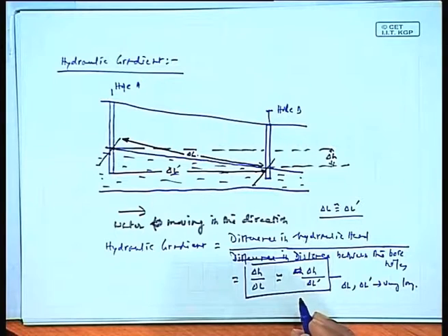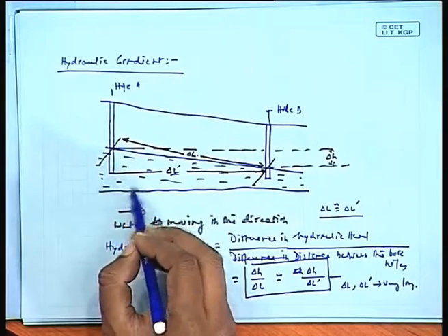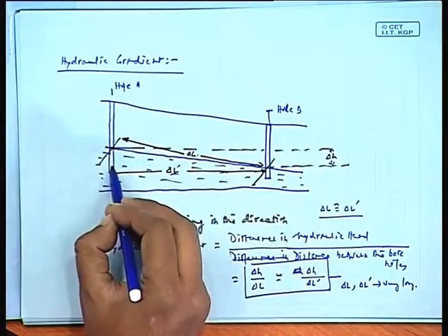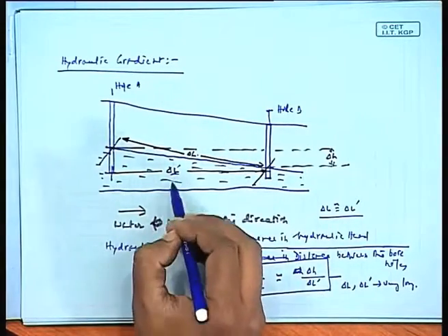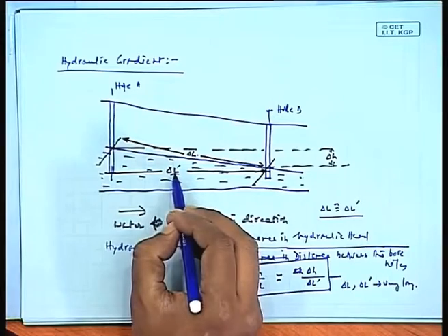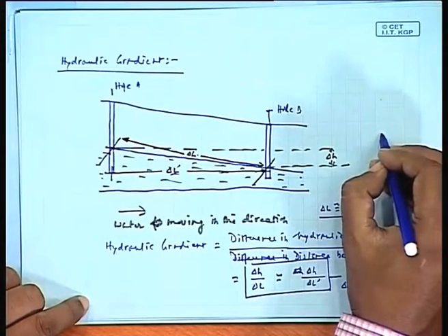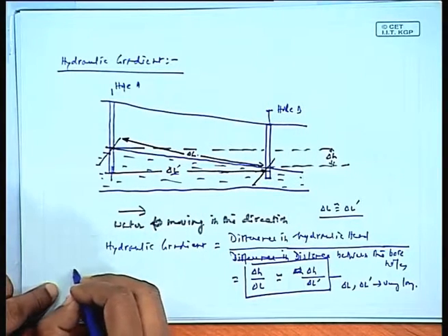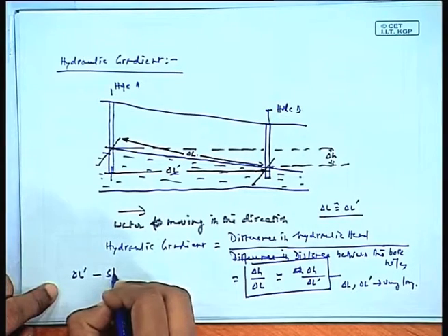But for almost all practical purposes, if not otherwise specified, this distance is what should be covered as del L dashed. Remember this. To make the correct judgment about the hydraulic gradient, del L dashed should be considered.